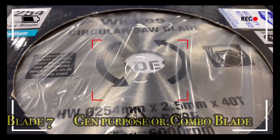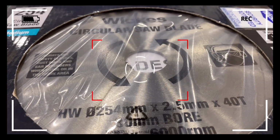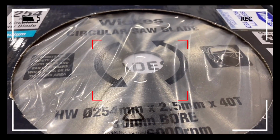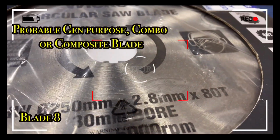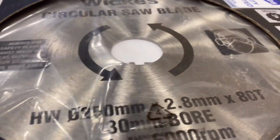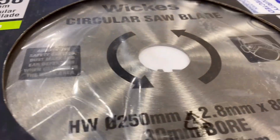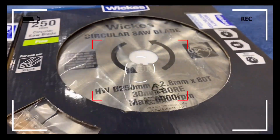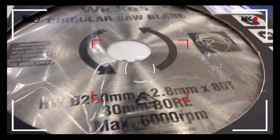The next blade has got a 10 inch or 254mm rim, a 2.5mm kerf, a 30mm bore, 6000 RPM and 40 teeth, so it could be a combo or a general purpose blade. The last blade has got a 250mm or 10 inch rim approximately, a 2.8 kerf and a 30mm bore, an RPM of 6,000 and 80 teeth, which implies that you could be getting a fine cut from this blade. It could be a general purpose, a combo or composite blade.